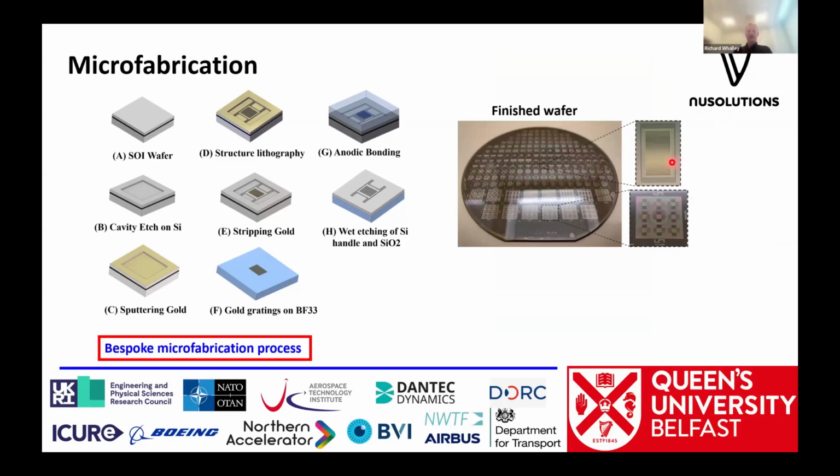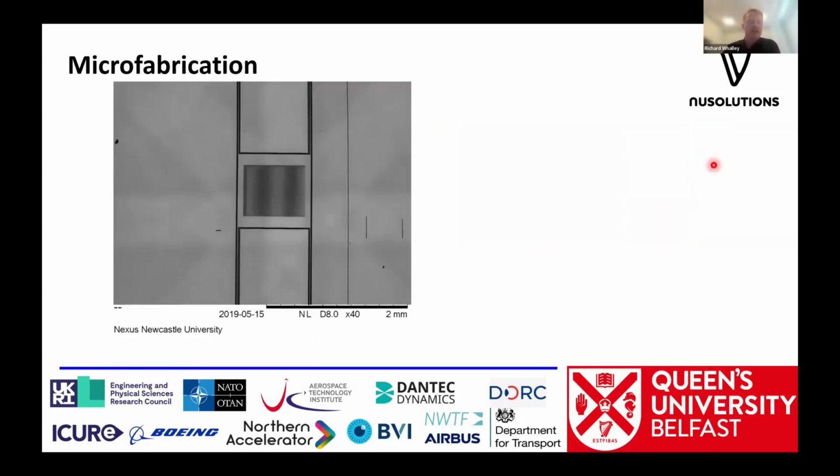And so if you take a look back and just squint a little bit, you can kind of see on this sensor here the dark bit and the light bit, and that's the Moiré fringe pattern that you can see. This is the serpentine design. And at the bottom here is some arrays that we developed, although today I'll talk more about the 1D sensors up here. And so ultimately we end up with a wafer, and then we chop that wafer up into our sensor dies.